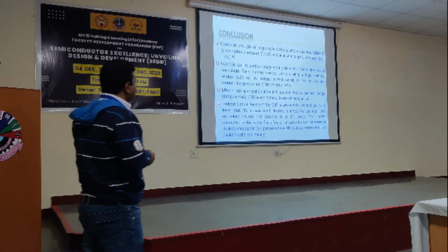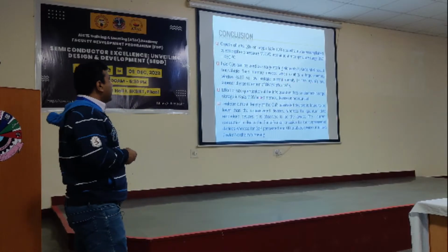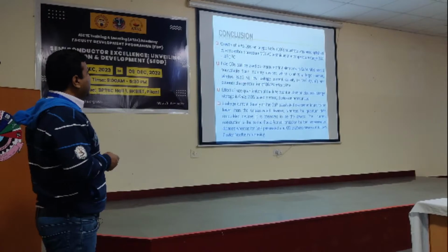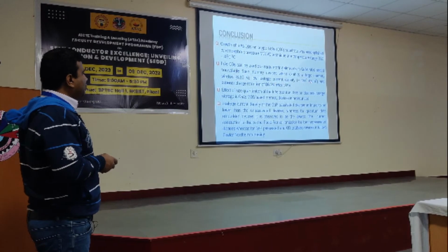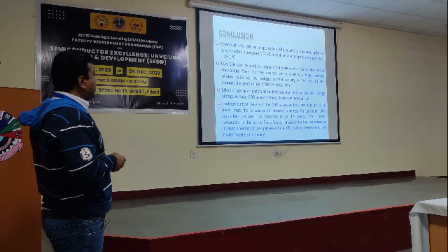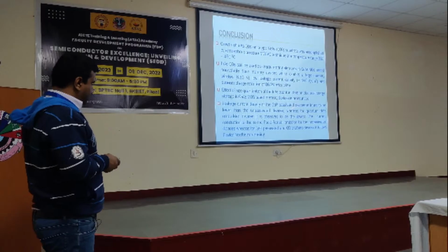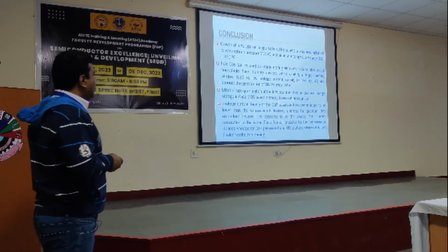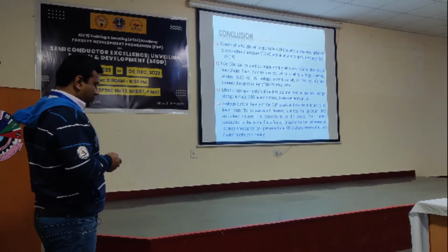Now, in conclusion, I can say that growth of indium arsenide as well as gallium arsenide substrate with a high-K dielectric present, in that case the maximum memory window found is 6.83 and a very low leakage current density, and charge retention around, as I told you, 90%. I also investigated the size quantization effect of size on the quantum dot, and I also analyzed the leakage current density in three kinds of devices.